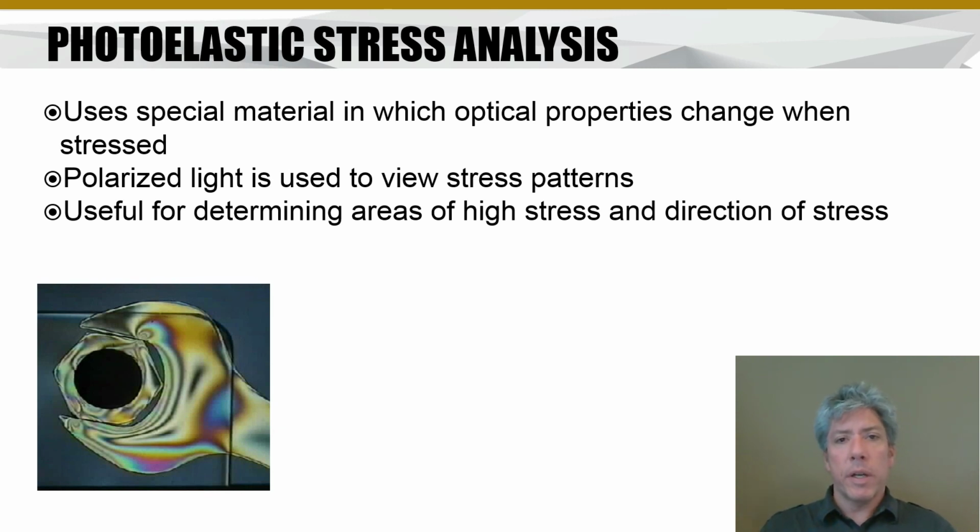Now we can do it with a polariscope. You can also take a photoelastic coating and put it on the part and see the same thing. But basically it just uses polarized light, and you can see where stresses are highest. And in fact, on this wrench and nut, it shouldn't be a surprise, you can tell the way this wrench is being turned. It's being turned clockwise, isn't it? How do you know? Well, notice the 2 points that are actually in contact on the nut with the wrench. They stand out like a sore thumb, don't they?